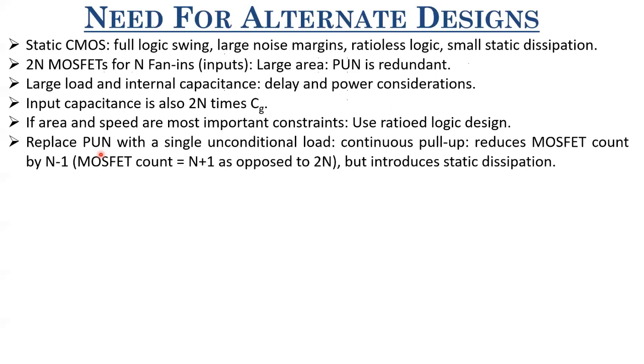But here, in the case of pseudo-NMOS logic, or a ratioed logic design, we replace this pull-up network with a single unconditional load that is continuous, continuously pulling up the output node. It's not like it is pulled up only when the input wants it to be pulled up. No. Here, the unconditional load is continuously pulling up the output node.